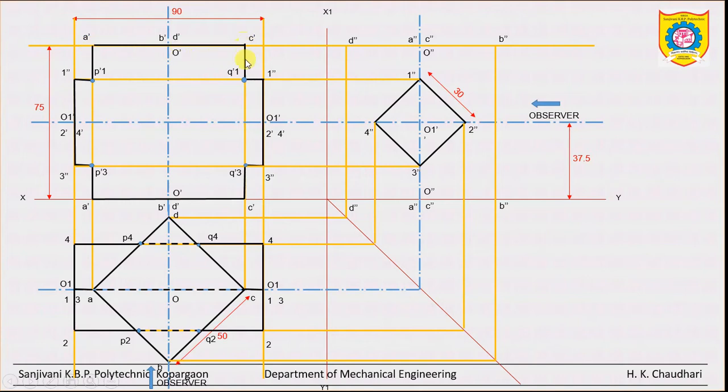This outline which is drawn thick, they are exactly out of intersection. Clear? All these edges are not taking part in the intersection, only the middle portion we have to draw now. So take the projection from point P2, and this projection passing through P4 also, so it is a common point P2 and P4.